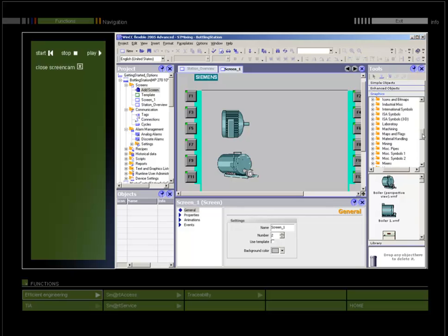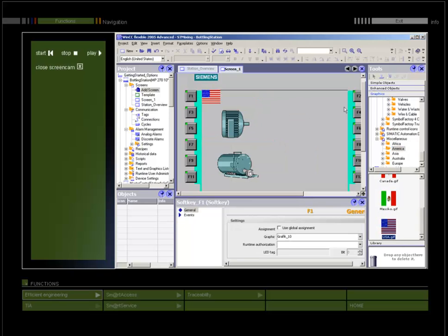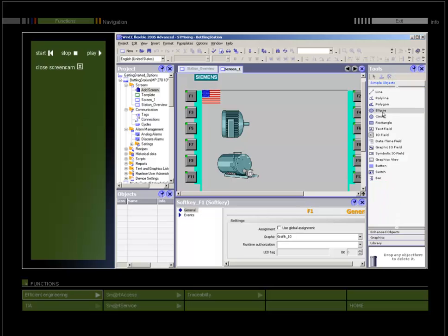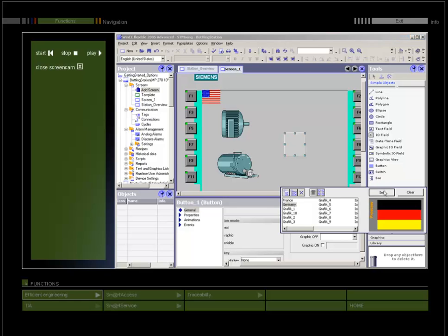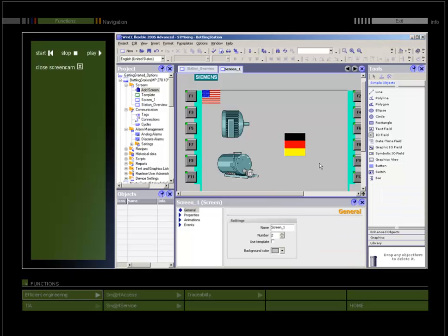The graphics that come with WinCC Flexible and your own graphics are displayed using a graphic browser and integrated in the project display using drag and drop. In the open display, for example, the placement of graphics in the work area using drag and drop generates a graphical display or enables the labeling of buttons or soft keys.